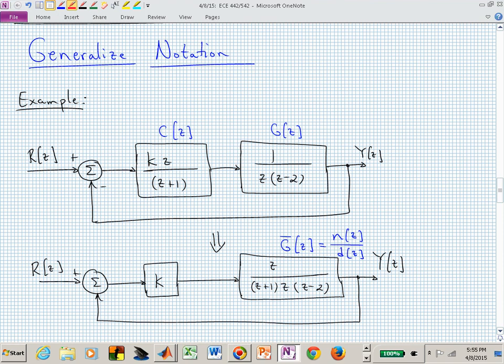And I've sprinkled in a pole and zero. Actually, I pulled out the zero shaker and I put it right at the origin in my controller. I pulled out my pole shaker and I put a pole at Z equal to -1. You will learn how to do this based on your knowledge of the root locus diagram.